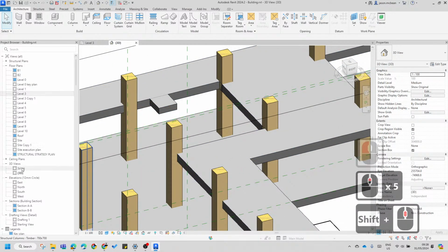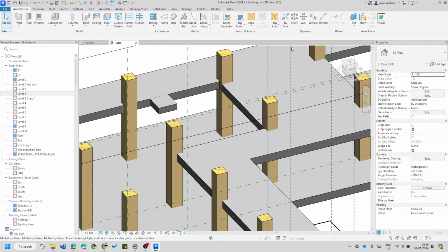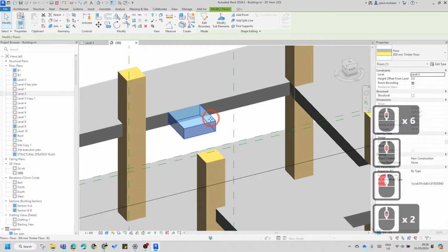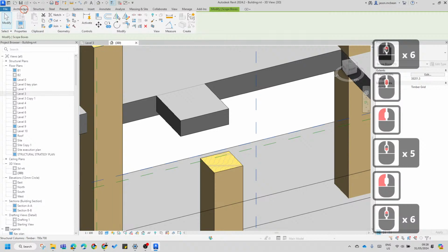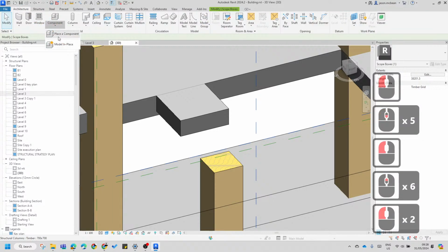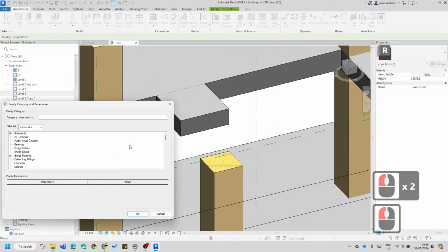Now you've got a 3D working view, so I might do it in that view and let's just see. For now, I'm going to create a generic quick model in place. You can do this using floor slabs and then steel beams, but I just want to see what I'm doing very quickly. I can delete this in-place family and I don't need it anymore because I'm just trying to prototype before I commit to building. Very easy. So I'm going to go to floors.